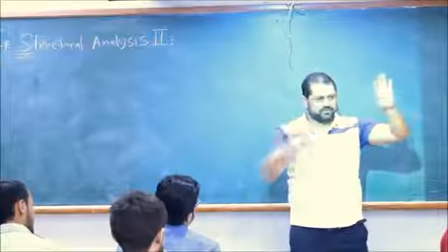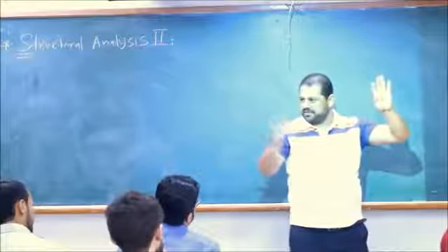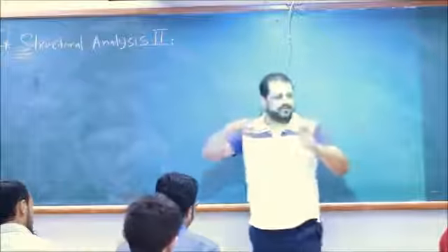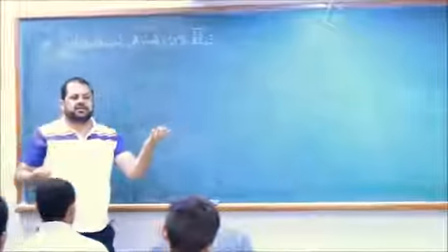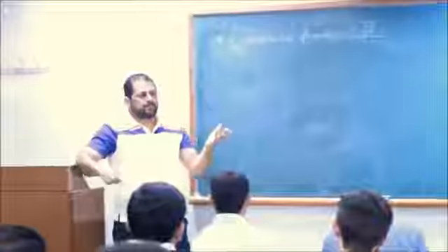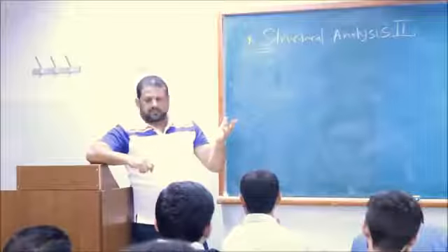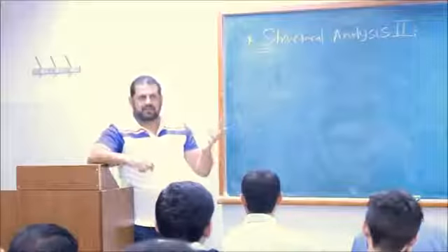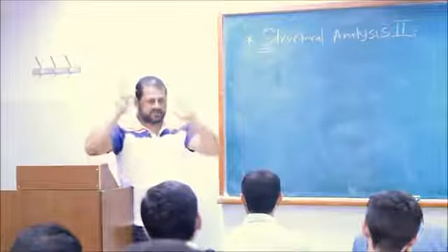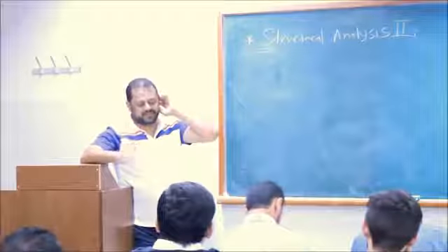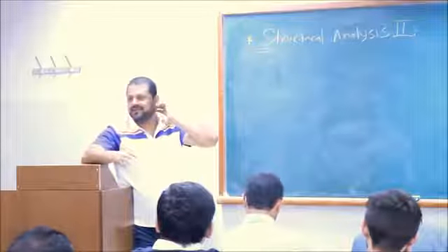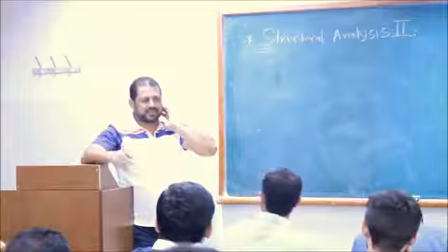Modular ratio. Did you guys take strength of materials? Okay, forget it. Maybe this is supposed to be in reinforced concrete. Anyway, E steel is how much in megapascal? 200,000 megapascal or 200 gigapascal. Anyway, I'm taking this to you at a higher level because usually I teach reinforced concrete and steel design, but this is structural analysis too.